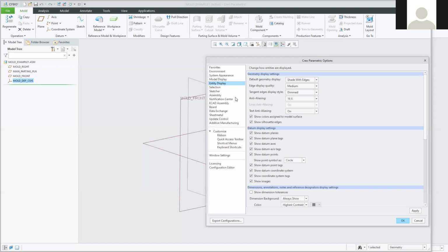Retrieval warning. You have insufficient access. So again, the virtual desktop version does have one or two quirks to it. You can cancel that error message or just say OK to it. Yeah, just click OK. It doesn't seem to damage anything too much. The other one that you might come across when you log into the virtual desktop is that it's telling you that you don't have write access to the temp directory on C. You just have to give it an alternative location to put its temporary files.